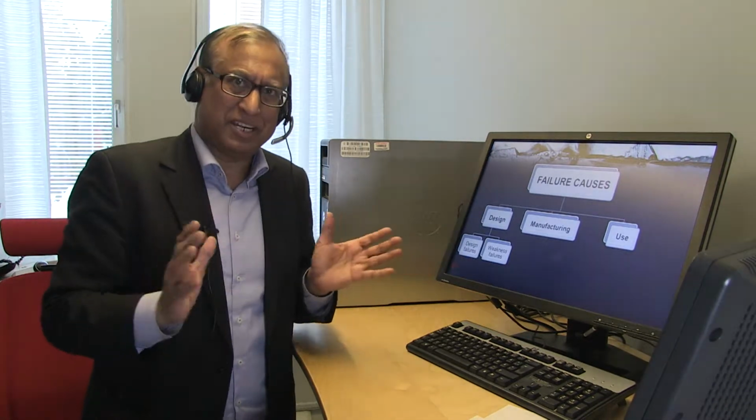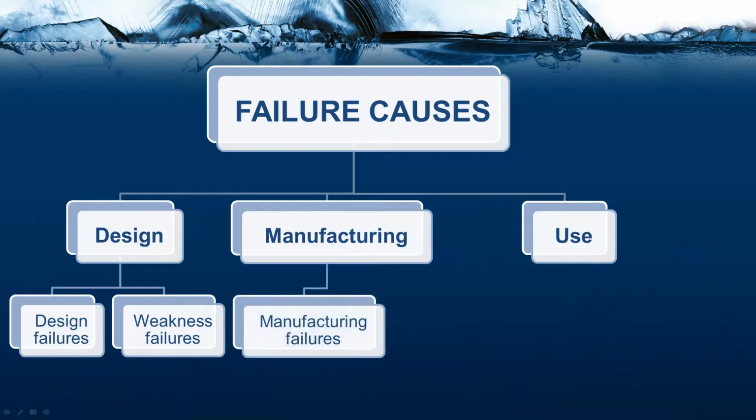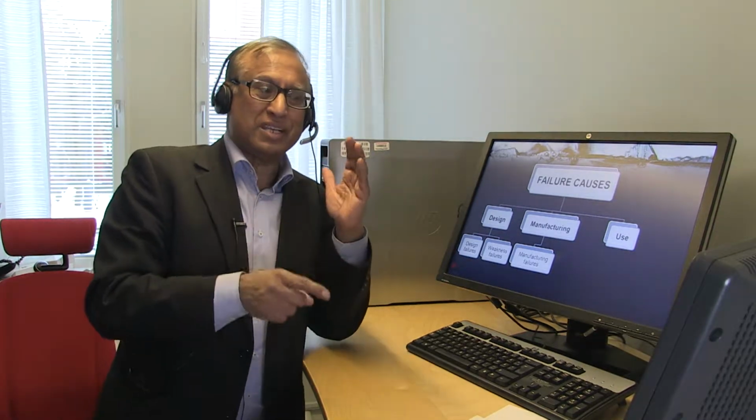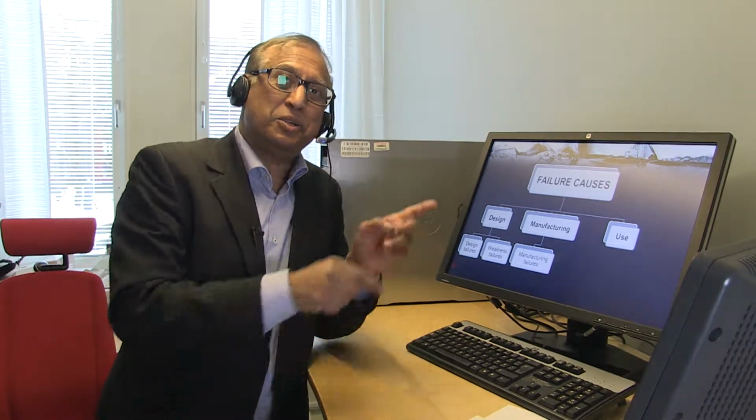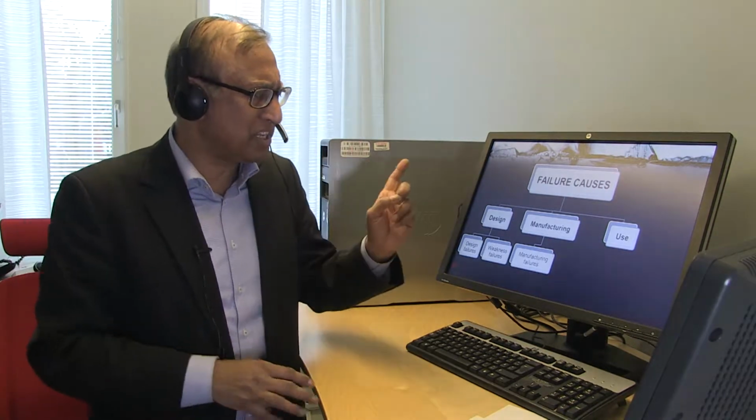But when the design is done and everything is perfectly calculated, it goes for manufacturing. There are some problems due to the machine or manufacturing system. If your machining tools are not perfect, it will lead to manufacturing problems. The tolerances will not be correct, or simply you are not able to weld because the designer, again, see how related manufacturing is to design, could not visualize that welding at that particular point is very difficult. You cannot do a perfect welding, leading to problems in manufacturing. You couldn't weld it in the right way, leading to failure during application. So manufacturing is also very important. Therefore, manufacturing and designer groups should work together. That's one very, very important thing.